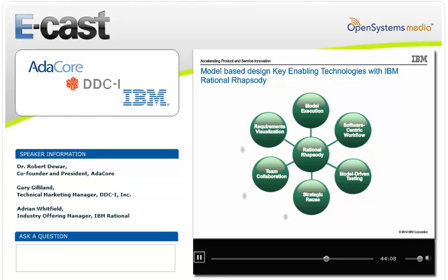And then, of course, the other aspect is bringing those graphical views to life through the use of simulation and execution. We can animate the diagrams so we can see exactly what functional mode we're in or what message has been sent between different parts of the architecture of our UAS. And this can be done in the modeling environment we use to build the model, or we can actually do it on the hardware itself through the use of hardware-in-the-loop simulation. We can even automatically build test cases from the model and then actually run them on the real hardware. So it's a great way to understand complexity and properly describe requirements and specifications as well.